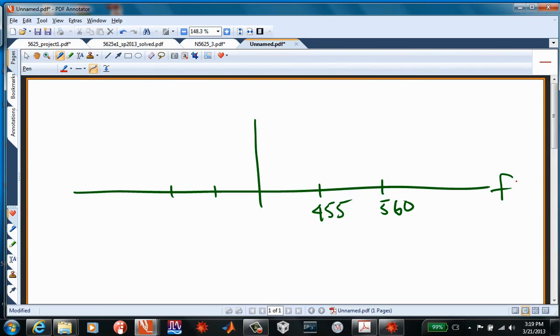And you were saying, suppose I choose the local oscillator below. So I have to get a local oscillator signal sitting way below that, maybe down at 105. So 105 produces a difference between here and here, which is at 455. And then you're wondering what makes 105 vulnerable to 455.